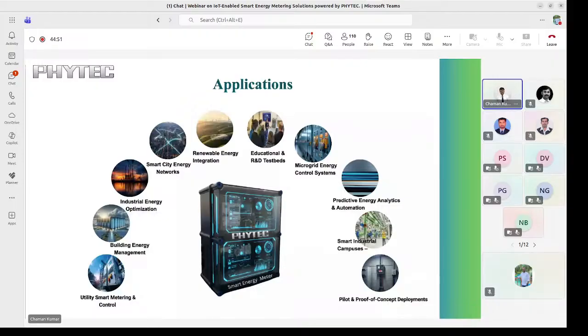Suppose I want to read the voltage. Voltage has a specific OBIS code. If I want to read the current, current has its own specific OBIS code. Any vendor who wants to expose data puts the data in that specific OBIS code at the register level. So if you want to fetch the data, you go to that register at that OBIS code, and you get the data. After you get and model the data, it goes to the application layer.